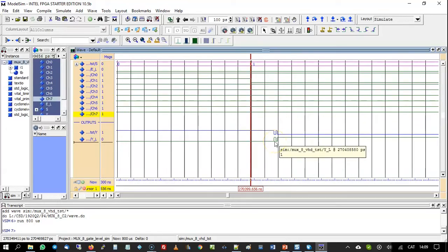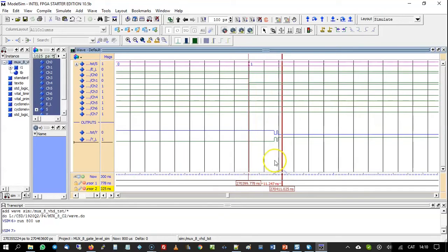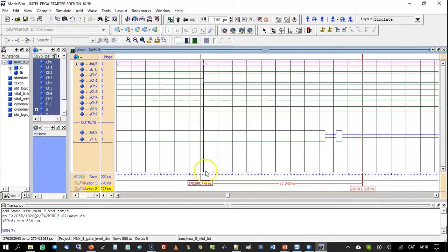In one cursor, you have the time when the input changes, and later on you see that the signal gets settled just some nanoseconds later. So let's measure that, adding a new cursor. You see, insert cursor. So you can move the cursor now. This is the beginning, 0 nanoseconds, and from this beginning to here is where you see the settling of the waveforms. You can even zoom that to the full screen.